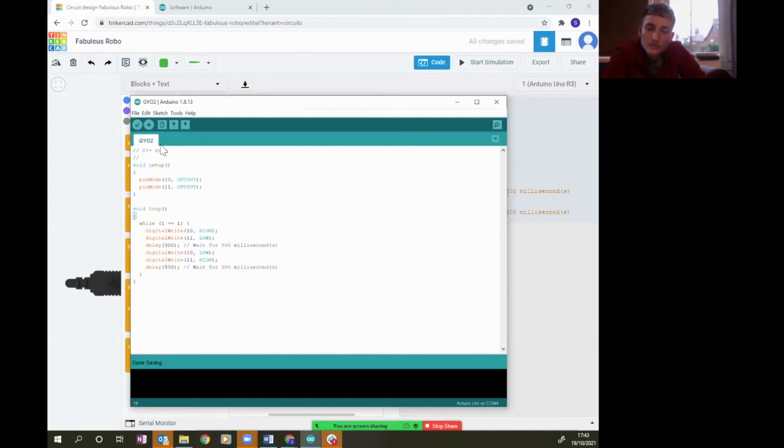You remember that last time we said it was really, really important not to change any components when your Arduino is powered in. And that's still really important. Now that it's plugged into the computer, we don't change any of them, do we, CJ? No, just leave them as they are. Yep. If we want to change any of them, we unplug it first. Very important. Otherwise you can blow the sensors. Yes, sometimes it causes them to break.